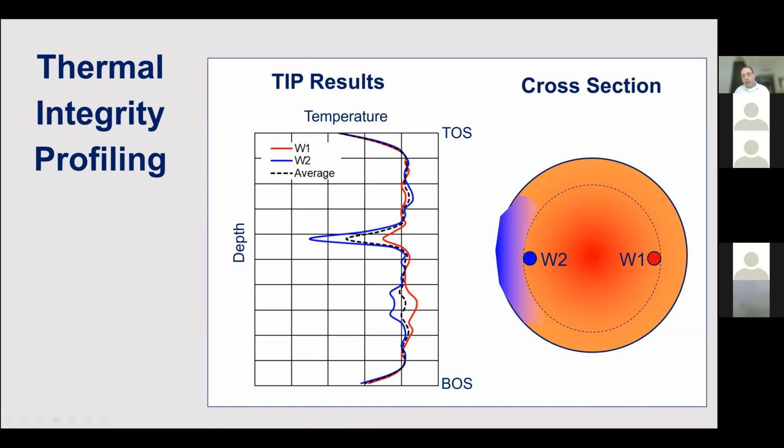Now, assuming that you have an anomaly, and that anomaly is closer to wire W2 than wire W1, wire W2 at that location is going to feel less heat compared to W1. And that signature is going to look something like this. Here, for example, there's maybe a cage misalignment. So when the wire signatures deviate, that's a misalignment. If you have a reduction in the temperature, this is a signature of an anomaly or a cavity, something that is not as hot as it should be.